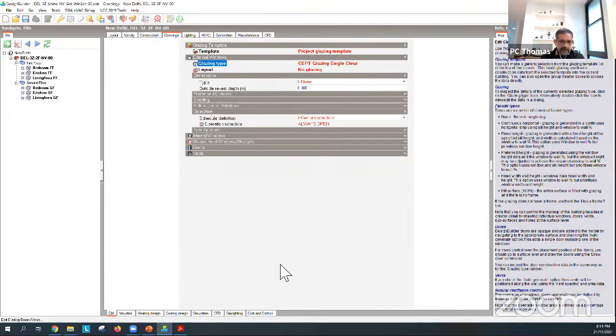And so what it asks you is, how do you control the opening and closing of windows? And there are some options here. One is that when it's occupied, open the windows. The other is you put a special schedule. So what I've done is that I've used this always open.